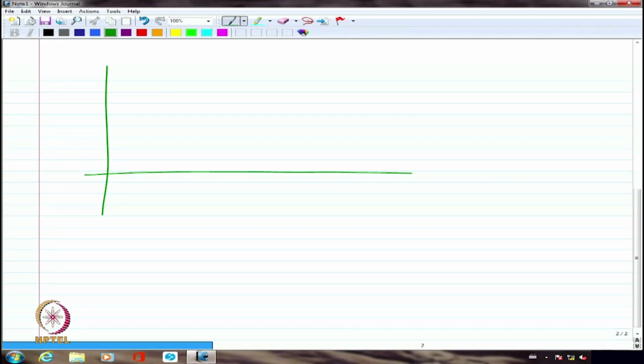So what I need to do is fix up 2 limits. One will be T max, one will be T minimum. These 2 are in my hands. I can decide based on the load condition. If the load torque is even less than T minimum, then I am assured to have an acceleration even when I am at T minimum.